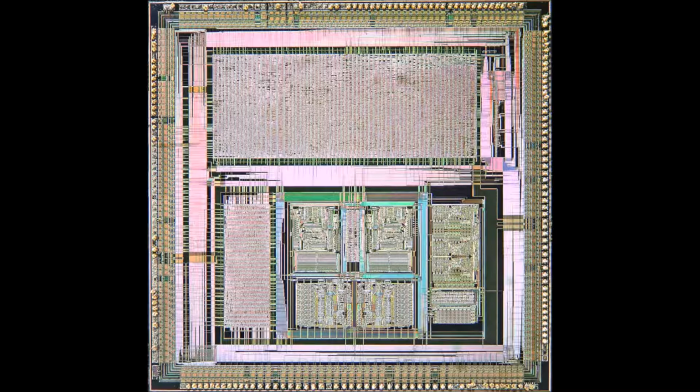We also have the disadvantages of the full custom design in an ASIC, which include increased manufacturing and design time, increased non-recurring engineering cost, more complexity in the computer-aided design system, and much higher skill requirements on the part of the design team. It is actually too hard to build an ASIC because of the thousands and thousands of gates it has.